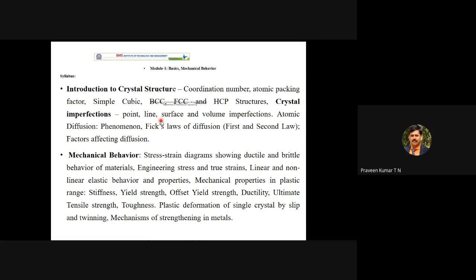There is also intermittent flow, like in an internal combustion engine. Only during some strokes is the fluid entered. In the suction stroke, only air, or even fuel, enters the cylinder, and only for a certain time. Afterwards it stops. That does not come under steady state flow. Those come under unsteady state flow, or we can say intermittent flow.